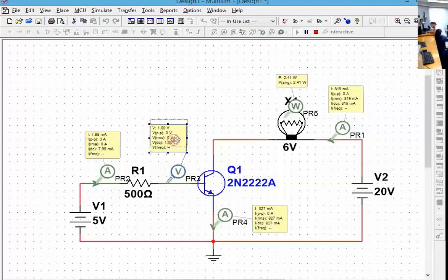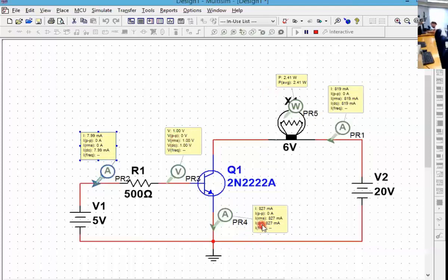We can do the math on finding out, which we will do at the end of this lecture eventually. But we can actually find out exactly what currents the base is having and the collector is having, so does the emitter. But effectively, that's the base current direction. This is the collector current direction. Both currents will meet, and this is the emitter current. That's why this arrow is pointing out. That's basically implying that this current is coming from the collector to the emitter, conventional direction, positive from the source to the negative.